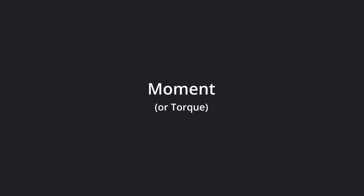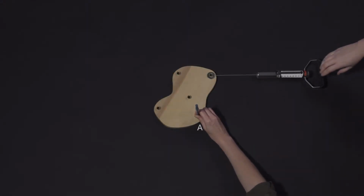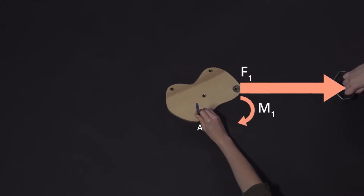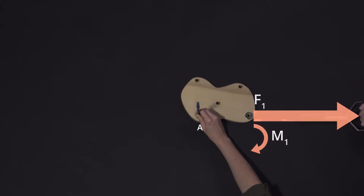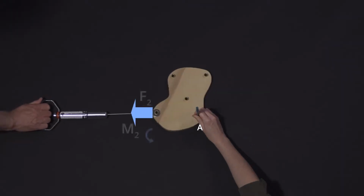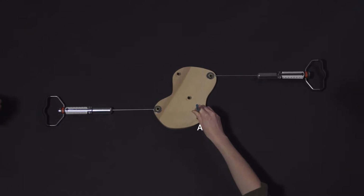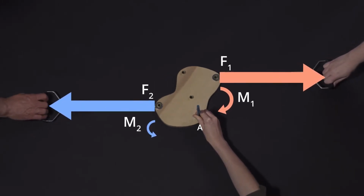To explain how forces can produce rotations, we need to introduce the idea of a moment, or a torque. Suppose we fix a point A on the model so that it cannot move. If we apply just the force F1, it will cause the wood shape to rotate clockwise about A. The force F2 would also generate a moment about A, but that moment would be smaller and counterclockwise. When the two forces act together, they produce a net clockwise moment.